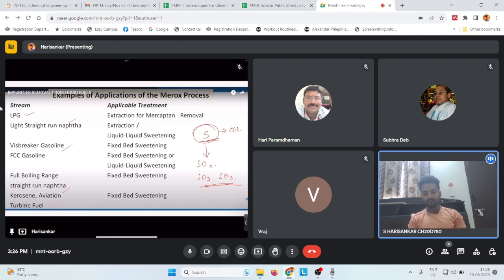And the same goes for nitrogen also. If nitrogen is present in your crude oil, usually this will lead to NOx emissions, NO2, NO3, and so on. These are also pretty harmful for the environment, and that is why removing both sulfur as well as nitrogen from crude oil is an essential part of the current day refinery process.